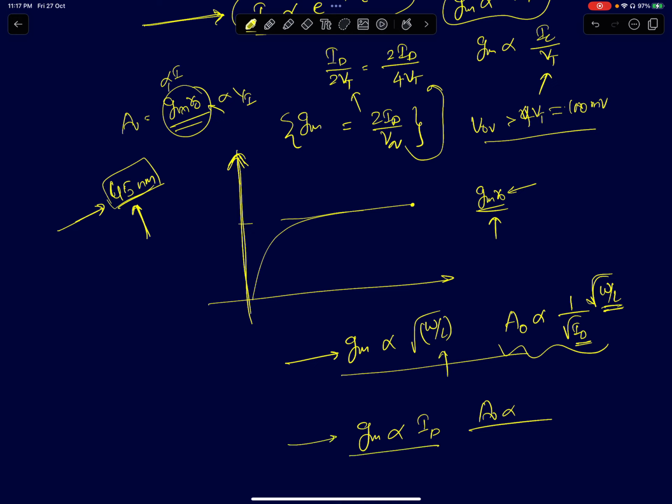So what engineers do, as I said, most engineers operate on some rule of thumb. Before you start a design, you will have some idea about a given technology. First you take a MOSFET and study it. You can diode connect a MOSFET, push a current into it, and vary its sizes. Let's say you push 1 milliampere of current and study the single device.